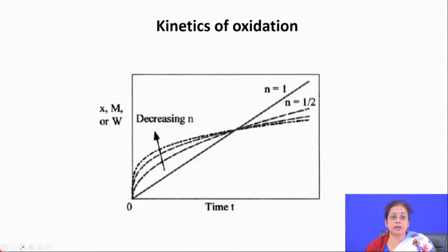If you think of the application of surface engineering in mitigating high temperature oxidation, you will find that in many cases the alloy is responsible for the oxidation mechanism. So, you have to think of surface alloying with a proper alloying element, particularly silicon, chromium and aluminum. These are three alloying elements which offer very good oxidation resistance.